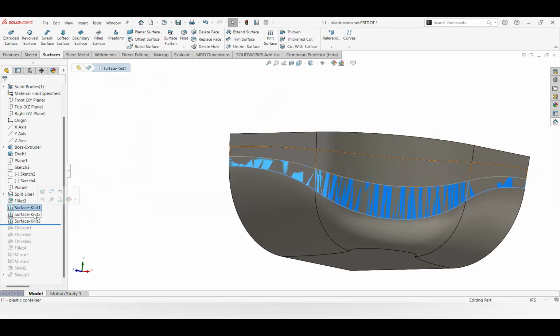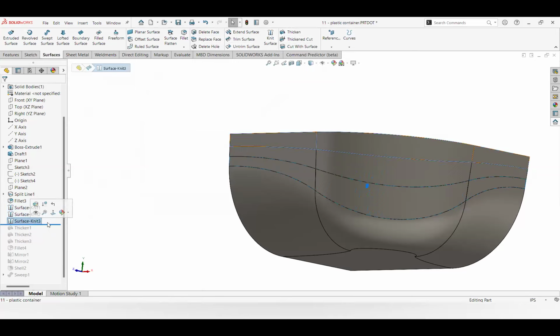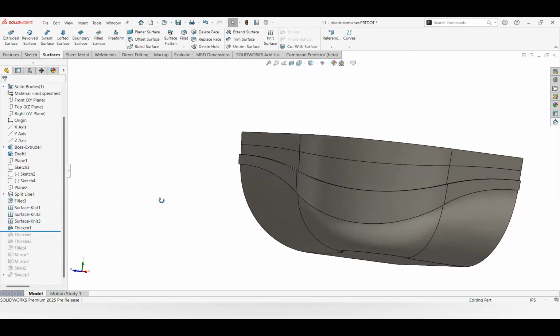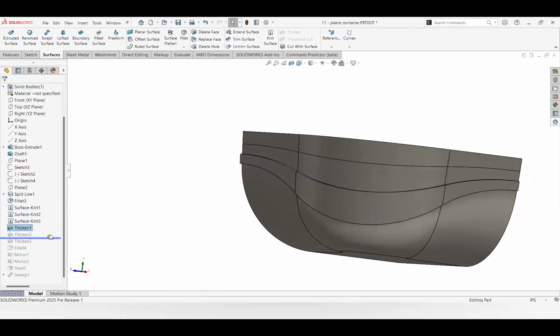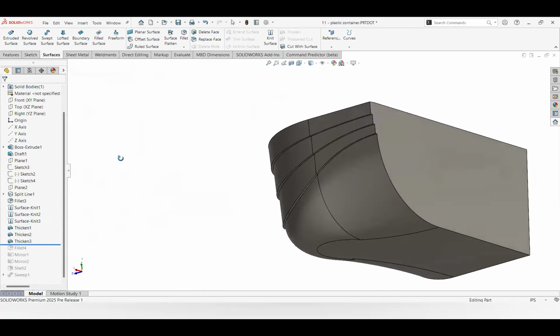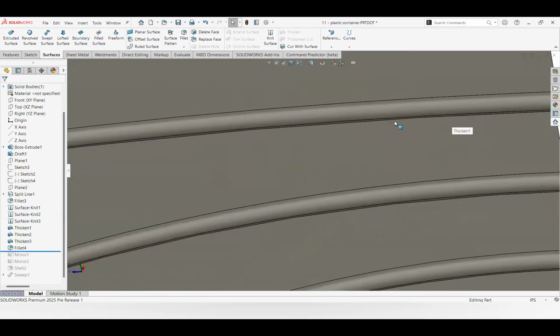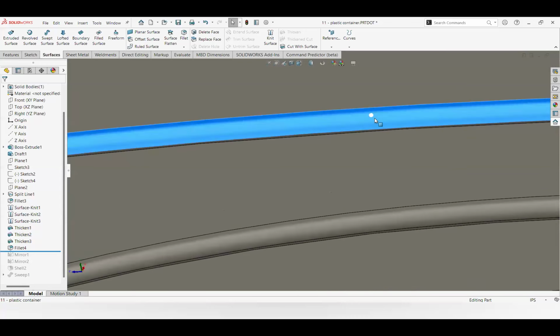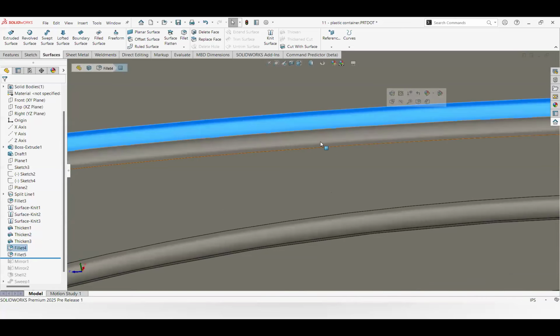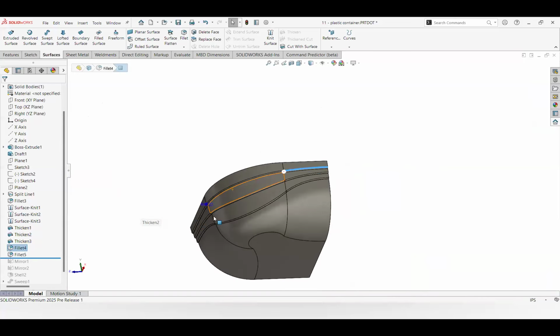So they created surface copies for all three of those sections, and then just did thicken operations with an increasing wall thickness. Okay, this is all still just a big solid bucket. Smooth that out with some fillets. The cool thing is this was done years ago when our fillets were not quite as robust, but now it would work very well to also continue that same fillet.